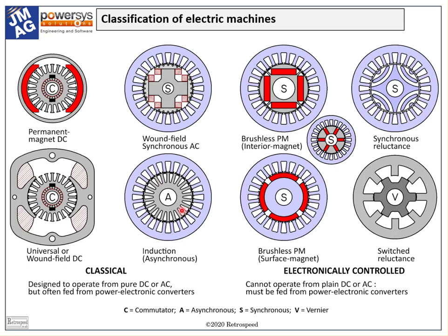The overview slide shows this stator only as a slotted punching, which doesn't do justice to the huge variety and ingenuity of the different winding layouts, but it does underline the fact that the AC stator is universal for the family of AC drives. It generally comes with a 3-phase winding in sizes above a kilowatt or so in induction motors or in smaller permanent magnet brushless motors.